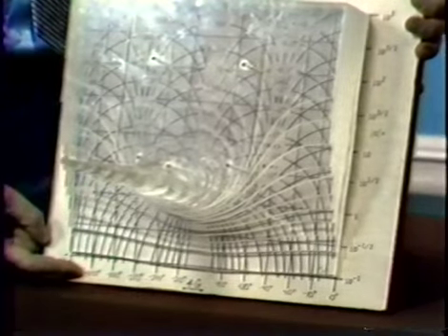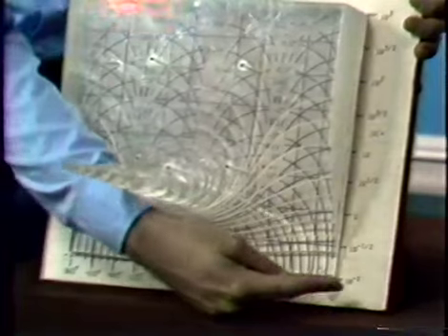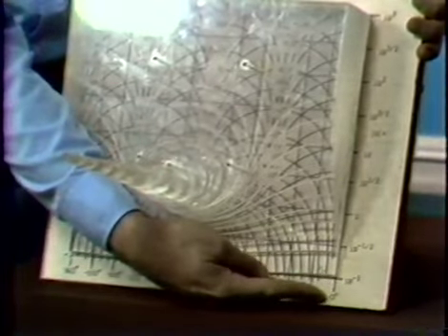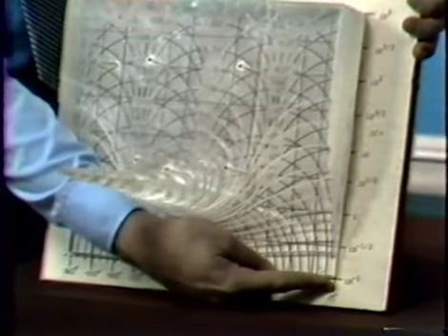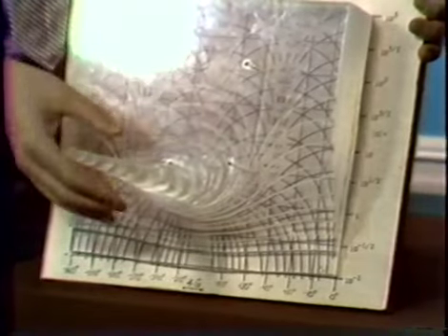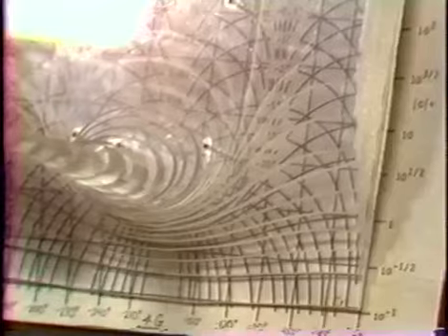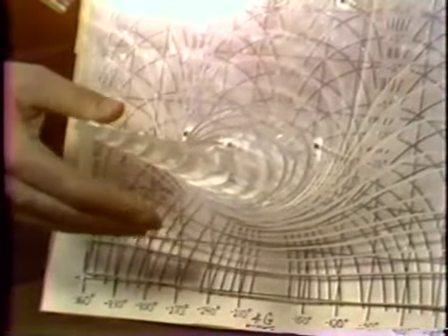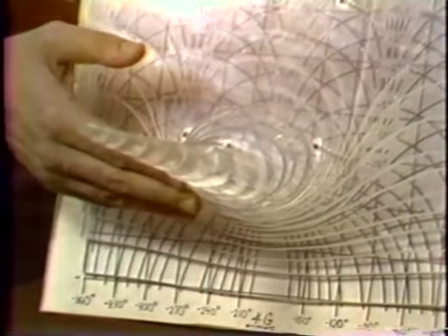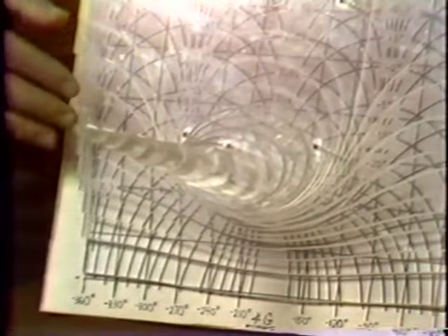Here we have an angle of 0 degrees, and an angle of minus 360 degrees over at this edge. And now the magnitude of G over 1 plus G is the height above the plane. We have sort of a contour map here, actually a three-dimensional contour map, and we get the value, the magnitude of G over 1 plus G as the height above this plane.